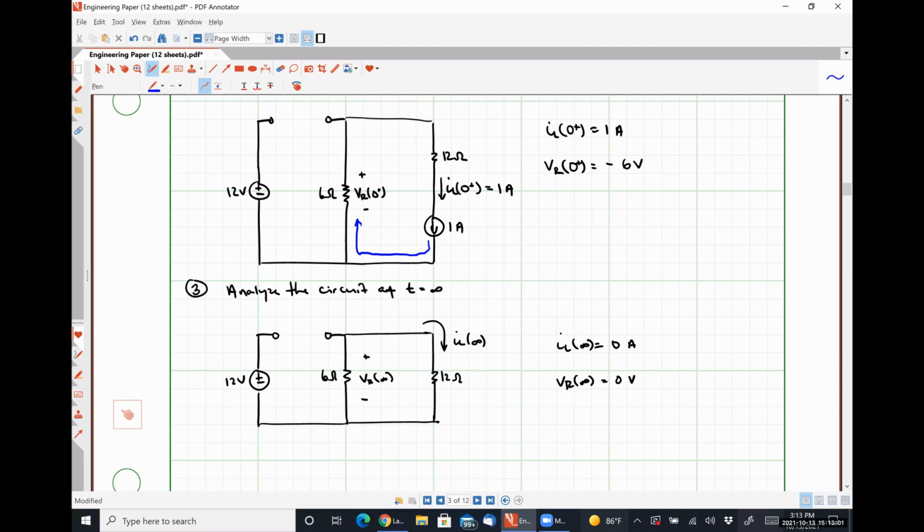All right. Well, then let's move along. The next thing that we are going to do: we know how the circuit behaves at its endpoints, right? We know how it behaves at the beginning of the transient condition, and we know how it behaves at the end of the transient condition. And we have mathematically shown that there's going to be an exponential decay, based on the resistor value that the inductance sees and the inductance itself. So what we need to do now is figure out what resistor value the inductor sees and what inductor value that equivalent resistance sees.